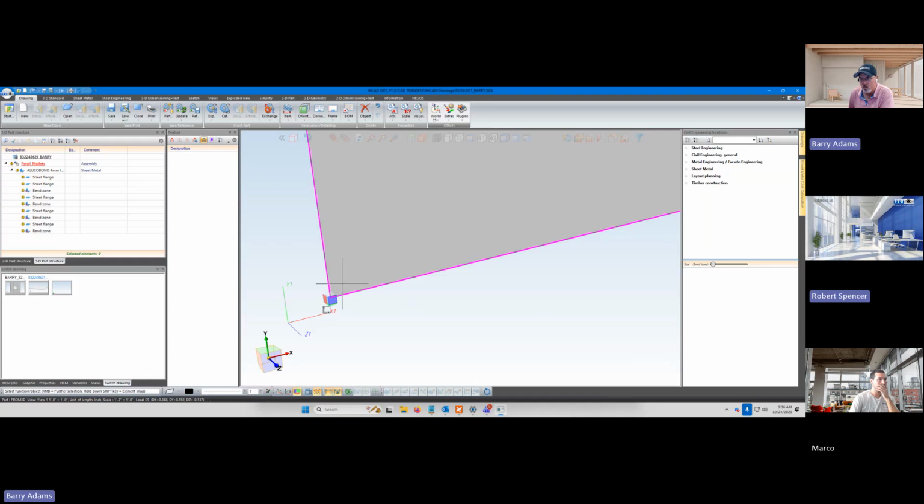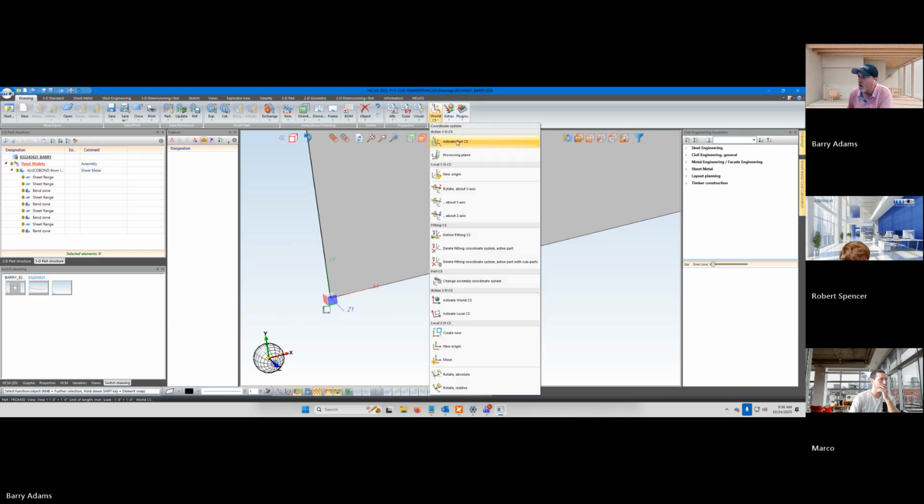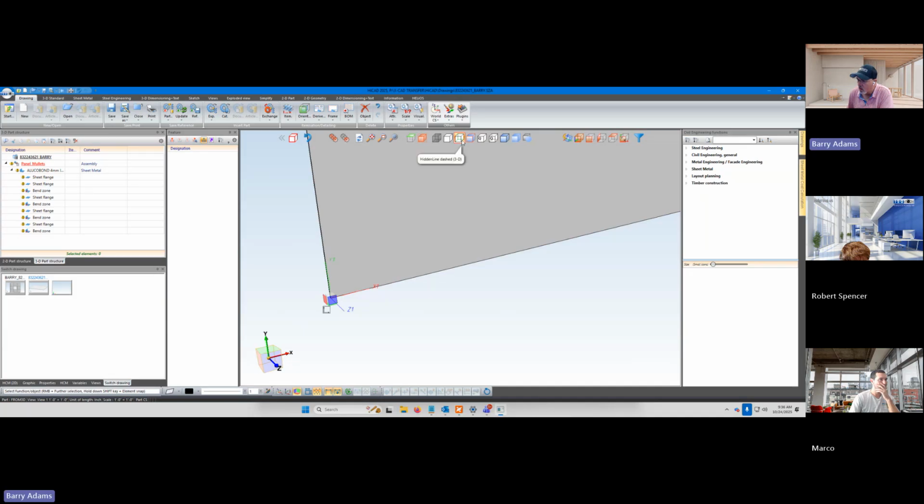So now repeat what we just did by going to the world, hit world or W. Now hit the drop down and just say Part CS. The assembly is still active. Okay, that looks right. It moved that over.